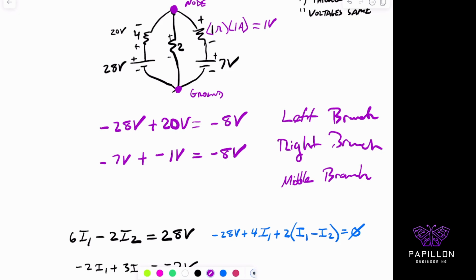And that 4 amps signifies that over here, this is going to be 4 amps. So if I'm reading it from the ground up, 4 amps times the 2 ohms will give us back the minus 8 volts. Again, it's 2 ohms multiplied by the 4 amps. This gives us back, if I'm reading it from the ground standpoint, minus 8. And if I'm going from the node top down, it's positive. But again, it all depends on how you're used to observing these problems; either form is fine. And you should be satisfied with noticing that our solutions make sense.